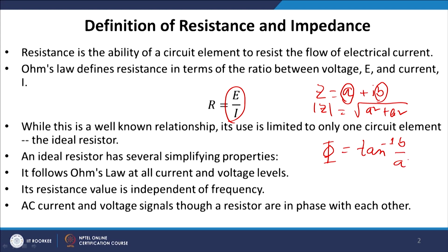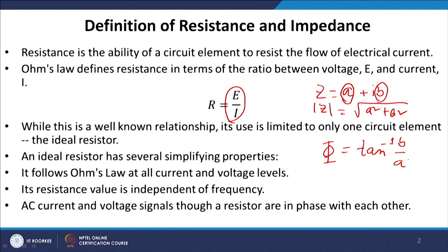Now, whenever we define a complex number, these two quantities are very important, its absolute value or magnitude or modulus, and its phase. So this magnitude |z| and the value of phase phi define a location or coordinates in the complex plane. Now, when you are talking about the current as a complex number and the voltage as a complex number, then obviously the resistance also becomes a complex number. So then we do not call it a resistance, but we give a separate name called impedance.